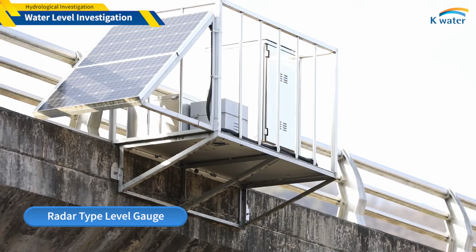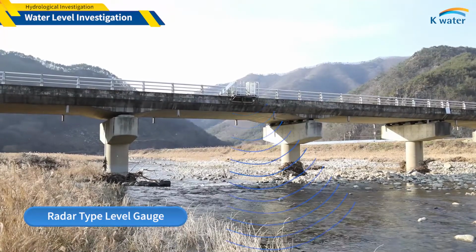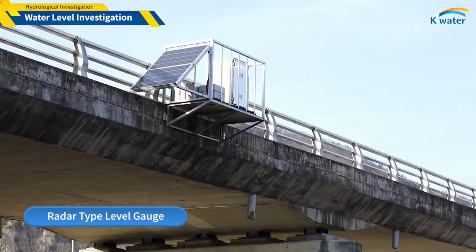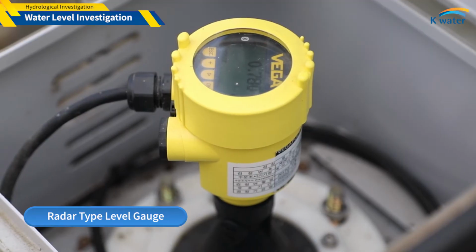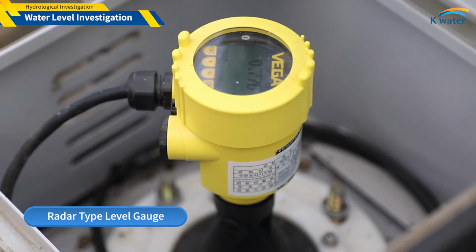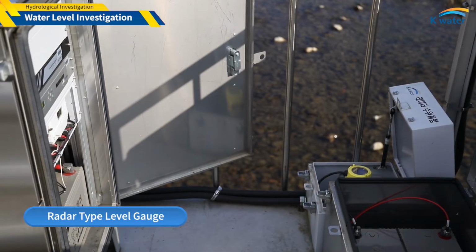The radar-type level gauge has a large error as the distance from the electromagnetic generator to the water surface increases. Therefore, the height of the installation point and the site condition should be taken into consideration. In order to accurately measure the water level, it is necessary to check the fixation of the water level gauge, foreign substances on the electromagnetic generator, and the power supply.